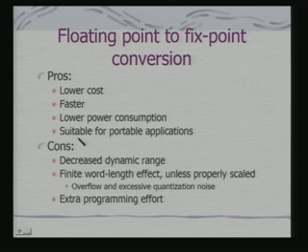When you do that, what are the advantages? Obviously, you have got lower cost, less computational overhead in terms of hardware, faster speed, and lower power consumption, and that is what is suitable for portable applications. And obviously, the problem is the finite word length effect: unless properly scaled, you have overflow and excessive quantization noise. And it requires extra programming effort.